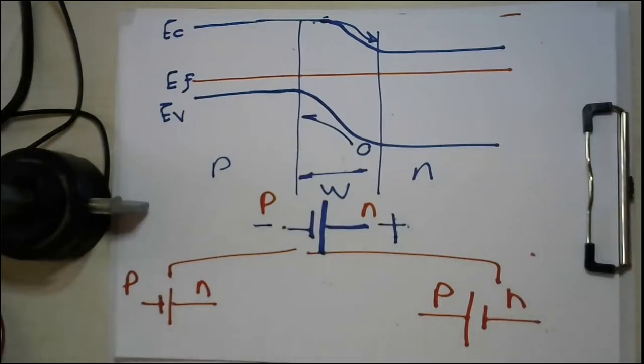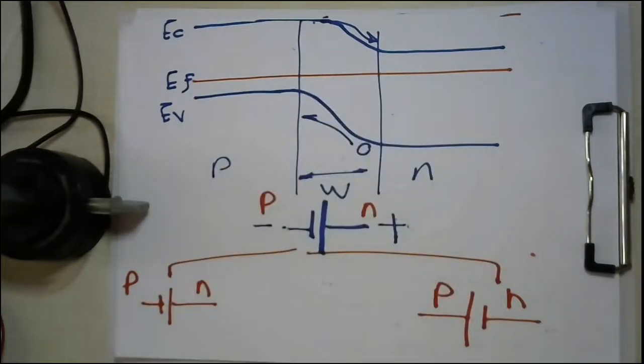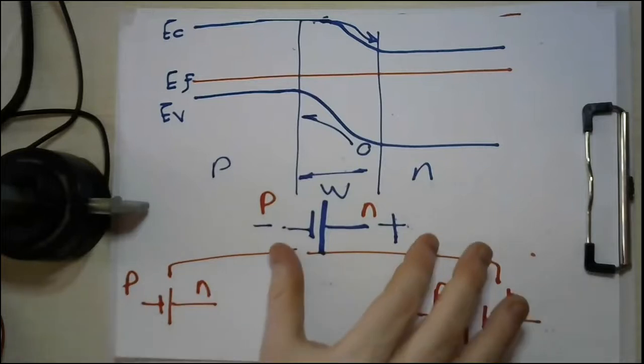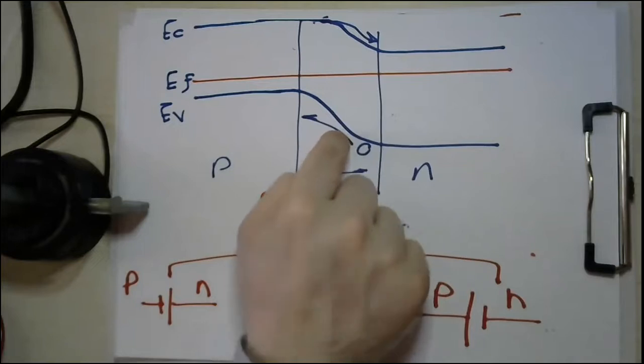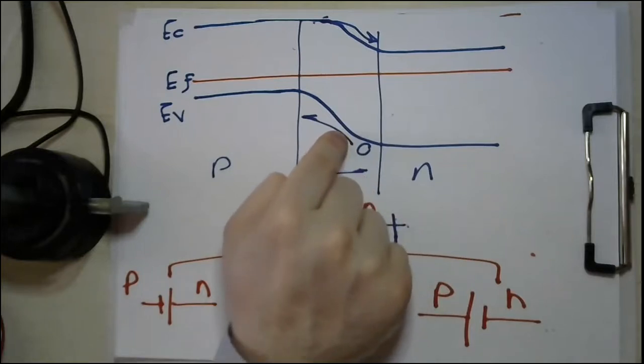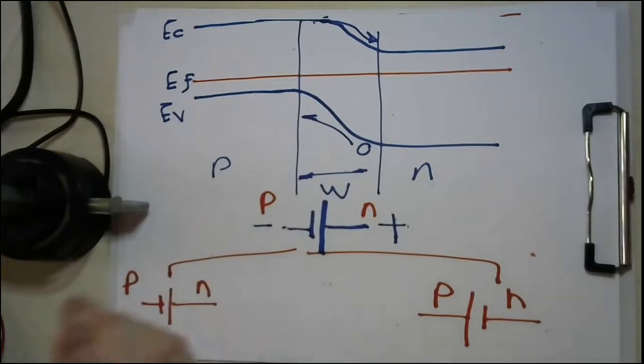So in order to make it easy and conceptual, and to get more insight into the PN junction, let's first start with the thermodynamic case, where we have this blue built-in potential. Again, this is not a real battery, it's a virtual battery representing the potential inside the semiconductor PN junction. There is no battery inside the PN junction.